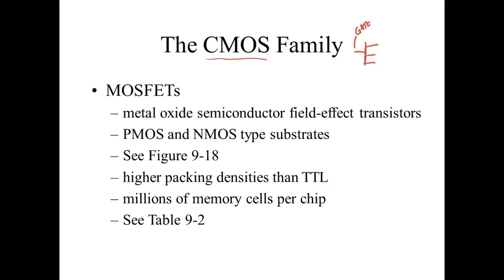These bands are designed with a resistance in them. Because if it didn't have a resistance in it, you would discharge when you put on the band, right? But it bleeds you off slowly. We can go over there and pop the CPU cover off the controller on the big Fanuc robot, and what do they have inside that thing? They got a static band that came with the controller, the static wristband.